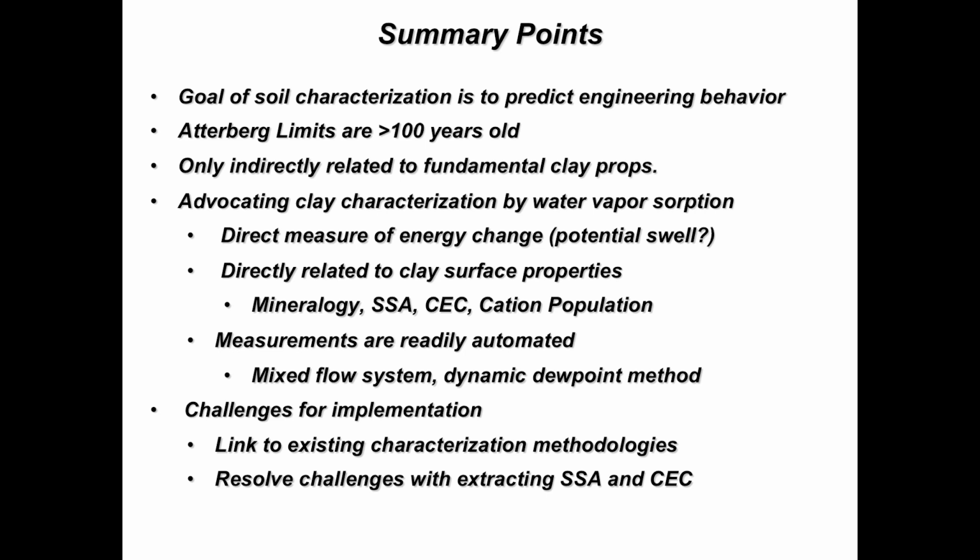Water vapor absorption is an approach that's relatively easily measured. We looked at a few different ways to do this using that mixed flow system that I pointed out, dynamic dew point methods that can obtain sorption isotherms for clays or other materials in 24 hours or so. And then finally we looked at some of the things that need to be done to implement this idea of replacing Atterberg limits.